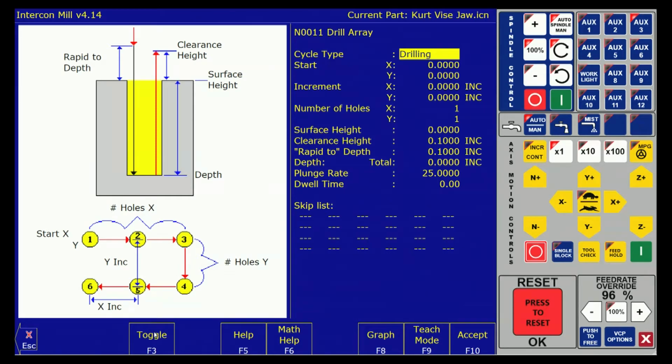So that's what straight drilling looks like. It's going to go to the full depth and come straight out. The problem for us doing this is it's going to make 2 chips as it goes down because of the 2 cutting edges. And the chips are going to be like 18 inches long. And they're going to wrap around the drill chuck and they're going to create havoc. So that's not good for us. If I had a 1/4 inch piece of material I was drilling, yep, I'd be all over this. But it's not going to work for us.